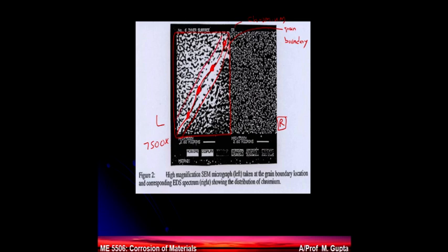That means you should have a zone in which you don't see any white spots, or their intensity will be extremely limited. We don't see those two features, which are a telltale sign of intergranular corrosion. So it is not intergranular corrosion. The report was sent to the court, approved immediately.